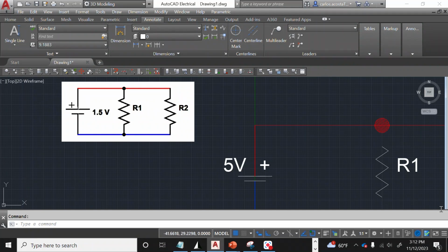It is going to be a DC source, could be a battery, could be a source. You can put a notation in and tell what kind of source this is. So the important thing is that in general, you need 1.5 volts for this circuit. Later on, if you're doing the schematics for production, you will give a part number and you will specify details about what amperage and what power you need. But right here is just 1.5 volts. Amperage and power is not given. Remember, the power is the voltage times the current. But at this point, it's a generic circuit to give you an example.